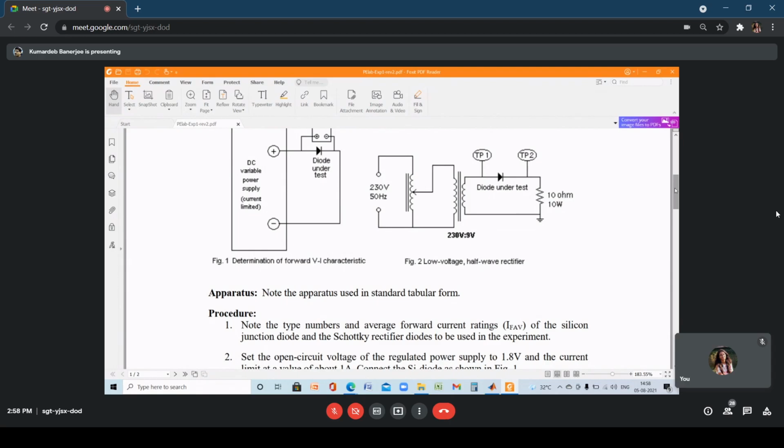So from these 5 points, you can draw one section of the diode curve. Okay. But for this section, instead of drawing the curve, you have to write down the approximate straight line fit through these points. So how do you find out the approximate straight line fit? You use a simple algorithm called the least square error method. Okay. So what is the least square error method? Since you have measured, you know what is your y for a given x. That means what is the diode voltage for a diode current.